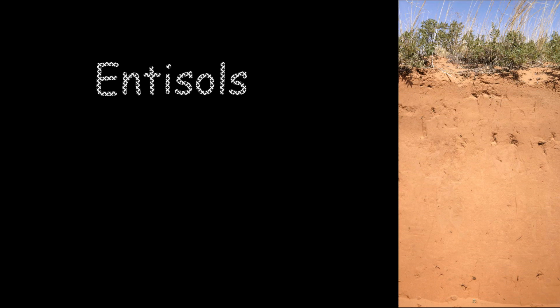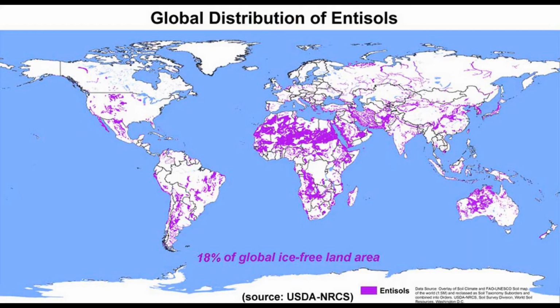Lastly, we have the largely distributed entisols. This soil order is the most weakly developed mineral soil without natural genetic B horizons. Most have an ochric epipedon and a few have human-made anthropic or agric epipedons. Soil productivity ranges from very high for certain entisols formed in recent alluvium to very low for those forming in shifting sand or steep rocky slopes.